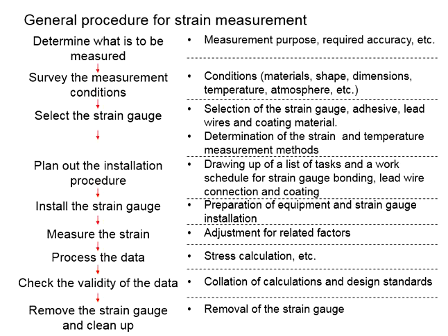Next, it will be the testing stage. You test the specimen and you measure the strength. Depending on the situations, such as the temperature, adjust the related factors accordingly to correct the results. After the measurement, it will be processing the data. Based on the strength acquired, you are able to compute the stress. Based on the readings given by the strain gauge, you can tell when the testing material yielded, and so on and so forth.